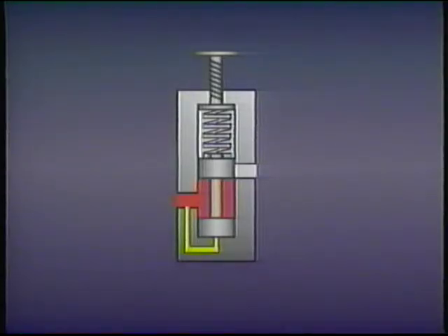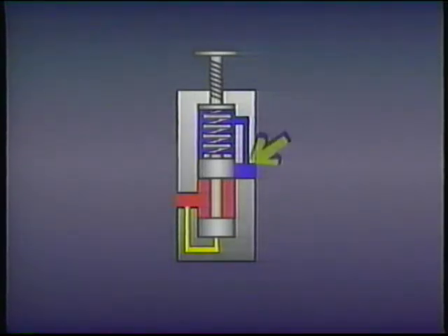All pressure control valves use some fluid for lubrication, but as a valve wears out over time, fluid leaks past the spool into the spring chamber. Excess fluid in the spring chamber will interfere with normal operation and must be drained. Many drains are internal. That means they empty into the secondary port. This works well for relief valves and other valves with secondary ports that return to tank at low pressure.